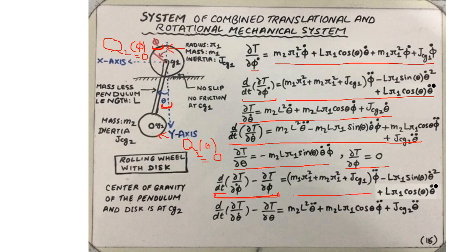And there will be a second Lagrange equation in which we are going to take the partial derivative with respect to theta dot and theta. That will give us this expression. So we have pre-computed these expressions so that by the time we have computed the other partial derivatives of the Lagrange equation, which involve potential energy and dissipation energy functions, we are ready to simply write down the final equations of motion.